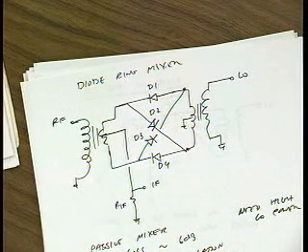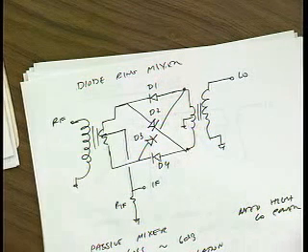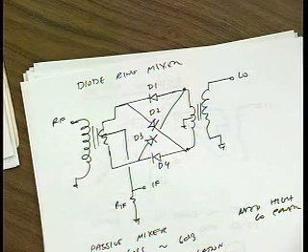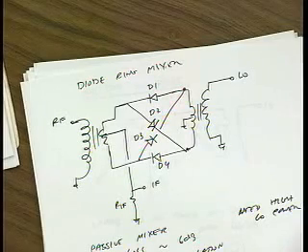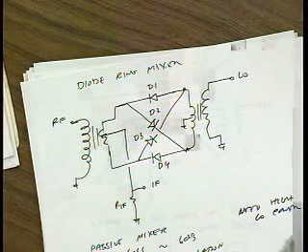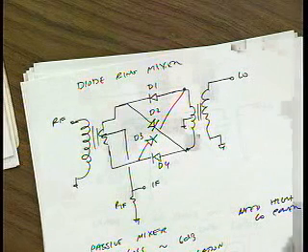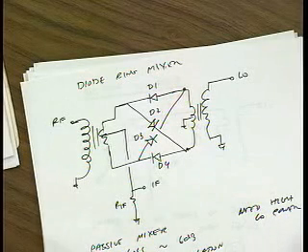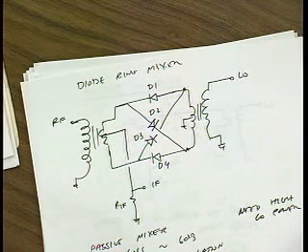Yes? You can. Yeah, we talked about that in I think the first lecture on mixers, right? We talked about how you could lock on to the nth harmonic of the LO. That's one way to try to get around that problem, but still the transistor needs to generate harmonics, right? And the harmonics are usually smaller than the fundamental. So if the fundamental gain is small, the harmonics are going to be tiny, and so you're not going to get much conversion gain.